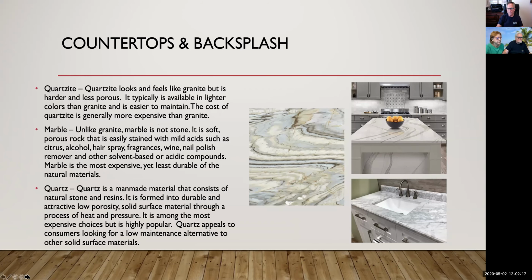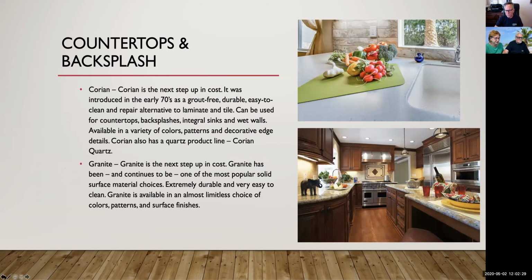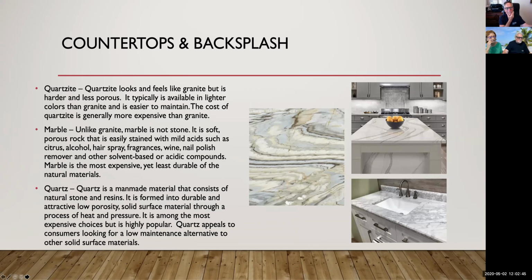And be aware too that granite only comes in slabs so big. So if you need something like that photograph that was very long, you're going to have two and book match them when the fabrication is going on. And book match is? Joining ends of two different slabs so the veining continues. Some continuity. Yes. Okay, quartzite.